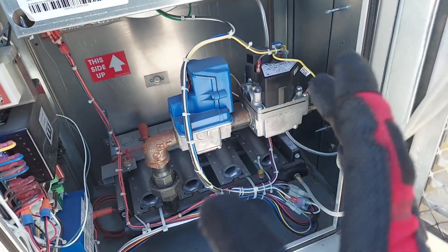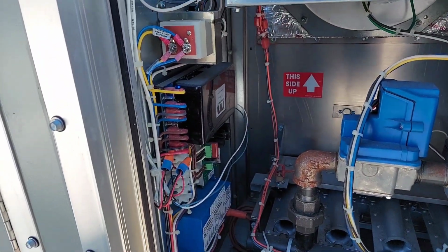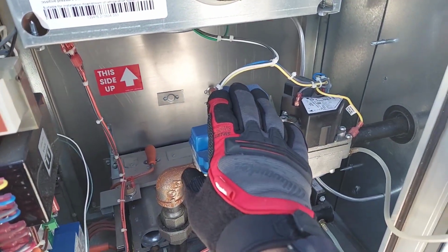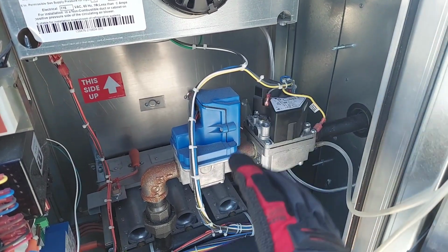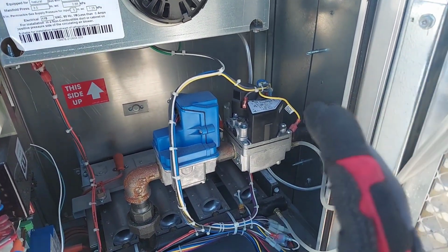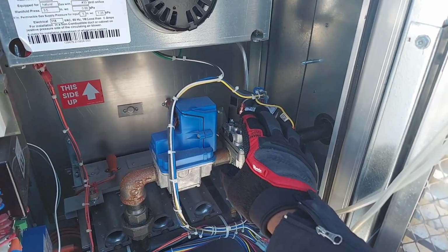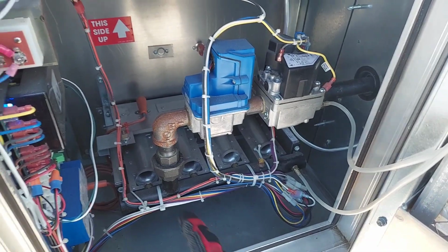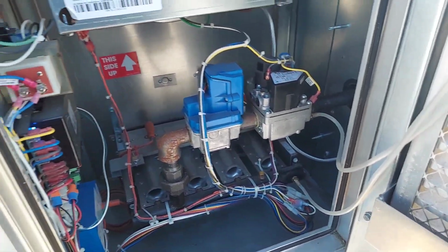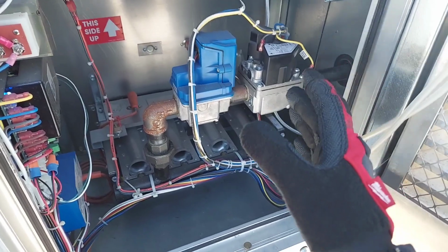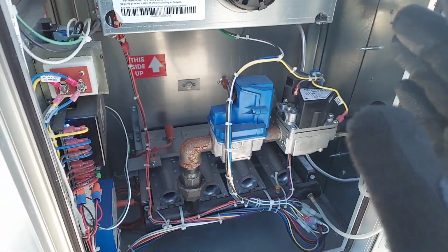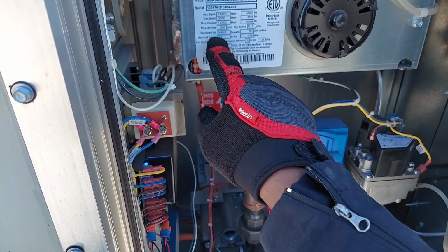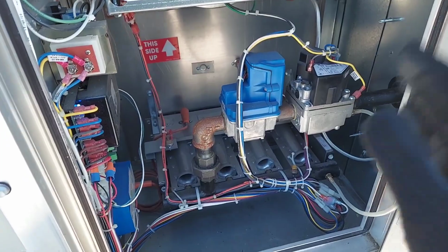Now this is a modulating furnace. The heating system can modulate. So this is the main gas valve, and this is the modulating gas valve. Based on how much demand, between 0 to 100, this main valve will open, and then this valve will modulate and control how much flow of gas enters the burner. Now obviously if you're at 50% modulation or 50% heating demand, you will not get 3.5. You get 3.5 at 100% PID, 100% demand of heat.